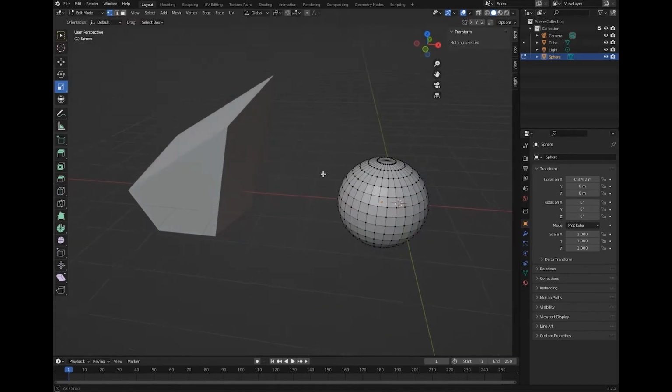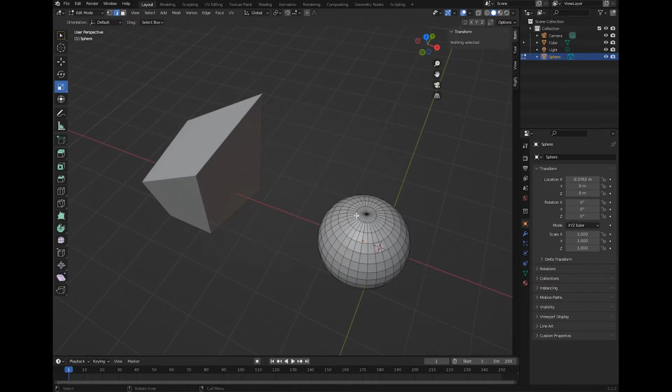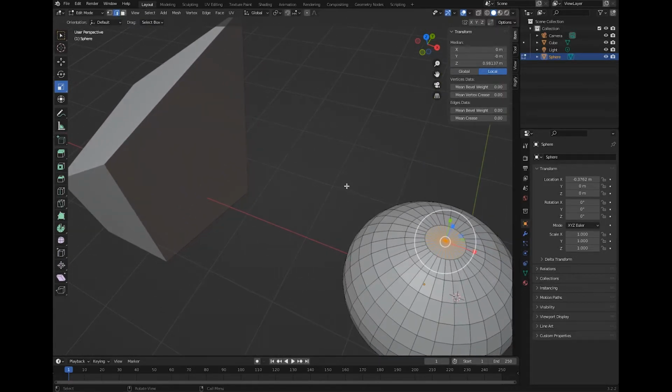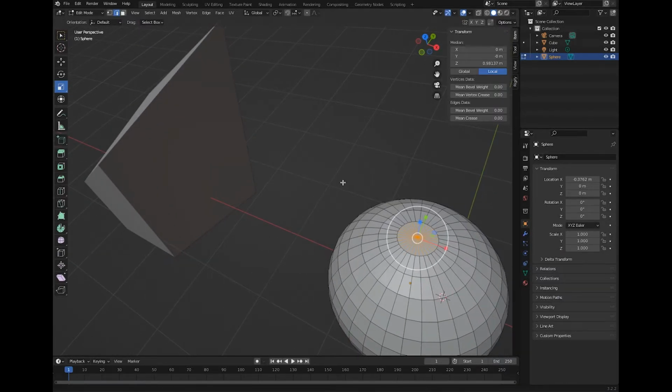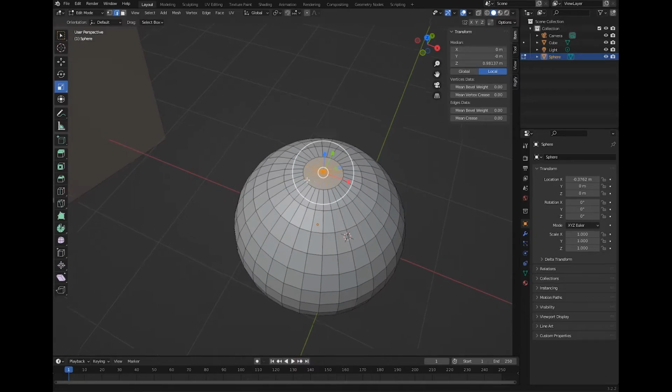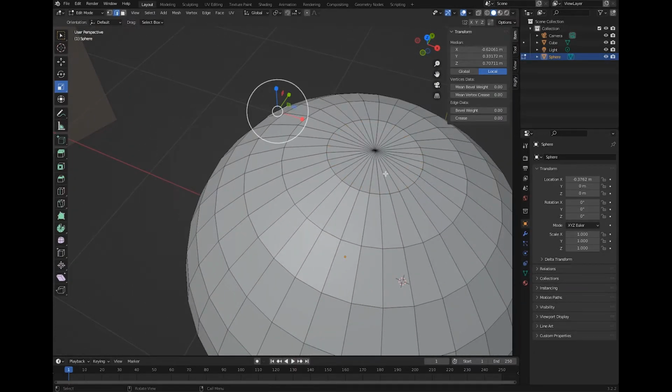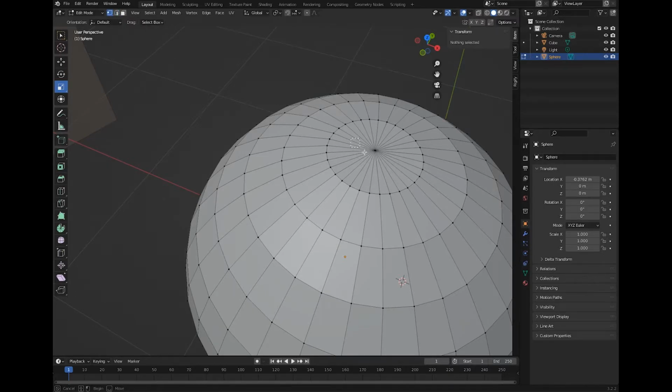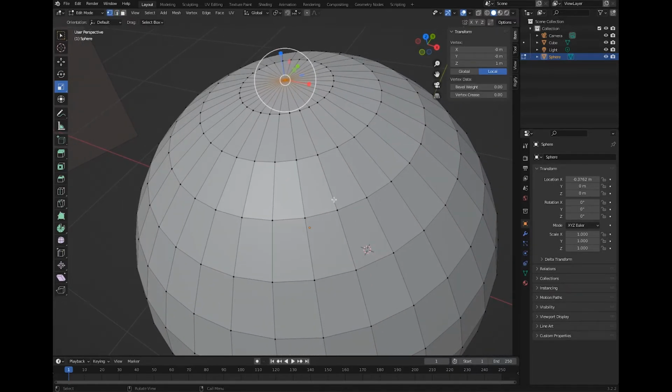And you can do the same thing. Let's just do one thing here. So let's say I'm going to select a vertex. Seeing the sphere here, you have one vertex only, right? Actually, you have a few triangles here at the top. We'll see that later on, how to change this to quads, because we normally want quads when we are modeling things. Okay, so now if I select that, I can press G.